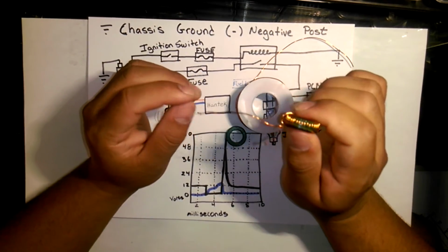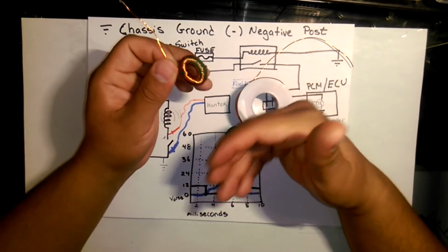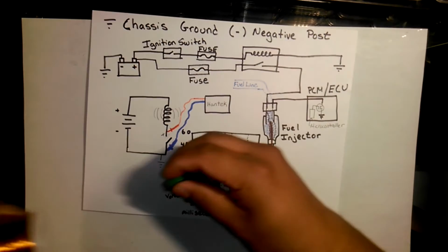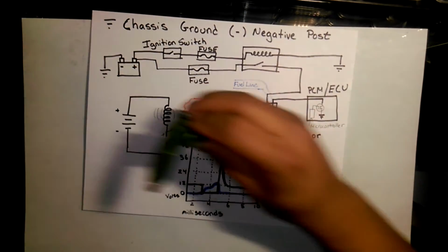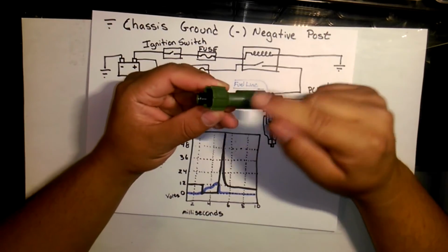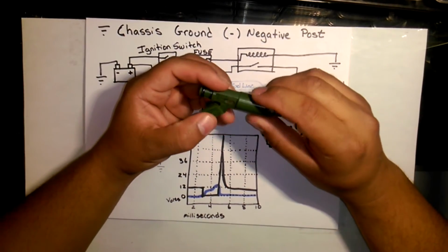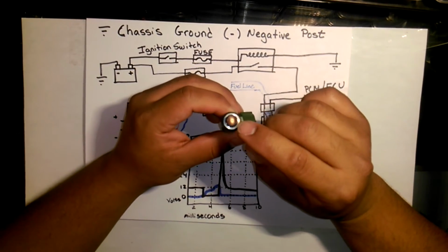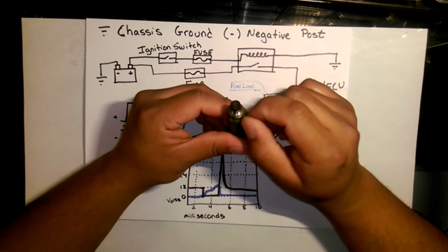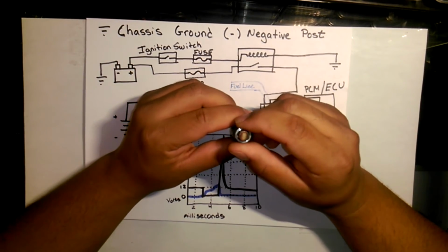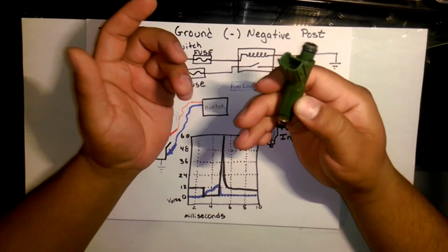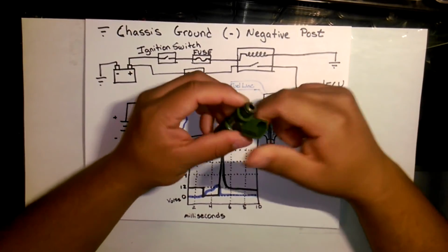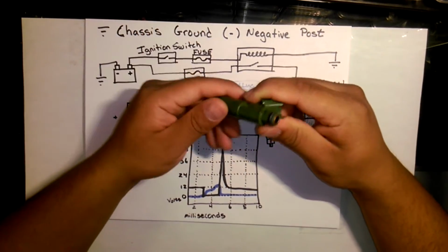And this is important for understanding why the fuel injector waveform looks the way it looks. Because inside of a fuel injector, there is a coil of wire. That's how they work. There's a coil of wire that becomes an electromagnet, and that electromagnet pulls on a pintle, and that pintle is what is blocking fuel from flowing. When the electromagnet pulls on that pintle, it allows fuel to flow, and that's how a fuel injector works. And of course, there's a spring inside, so once electricity stops flowing, the spring forces the pintle back down, and fuel stops flowing.